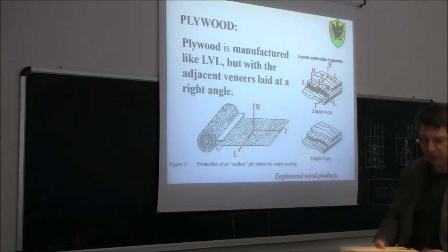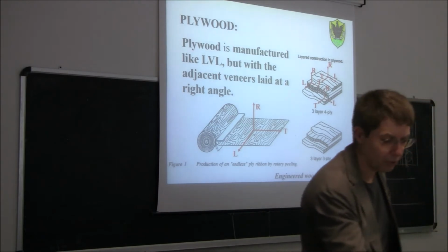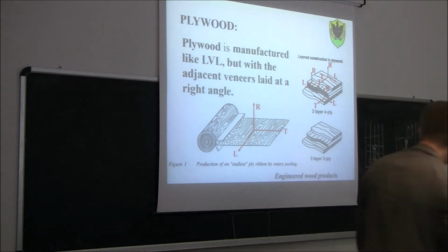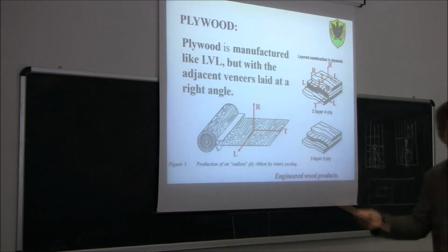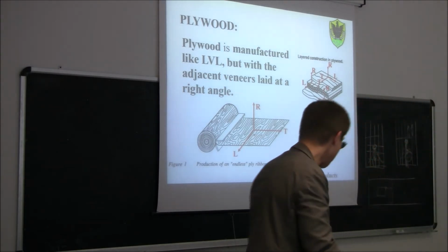Okay, now I'll give you this one so you can play a little bit. Just be careful because in the direction perpendicular to the grain, they are much weaker. So don't force too much, because otherwise, you see, this is a piece that was forced a little bit too much by some of your colleagues, and now I have one piece here, one piece in the other. Okay?